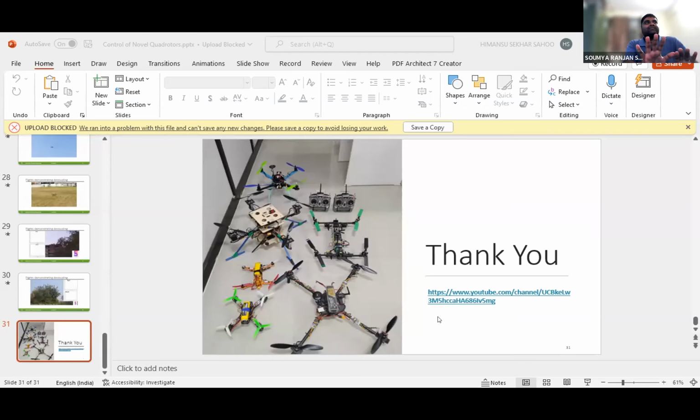With the tilt design that I showed you at the end, where we can have arbitrary attitudes and arbitrary position control with all the tilt angles decoupled, for such quadrotors I'm confident that we can land on such platforms. I have to just demonstrate it. But in the case of helicopters, this attitude decoupling from position is not possible, so it is a difficult problem, but I'll be happy to work on it. And I think Professor Abhishek's team is already working on such a problem, if I'm not wrong.